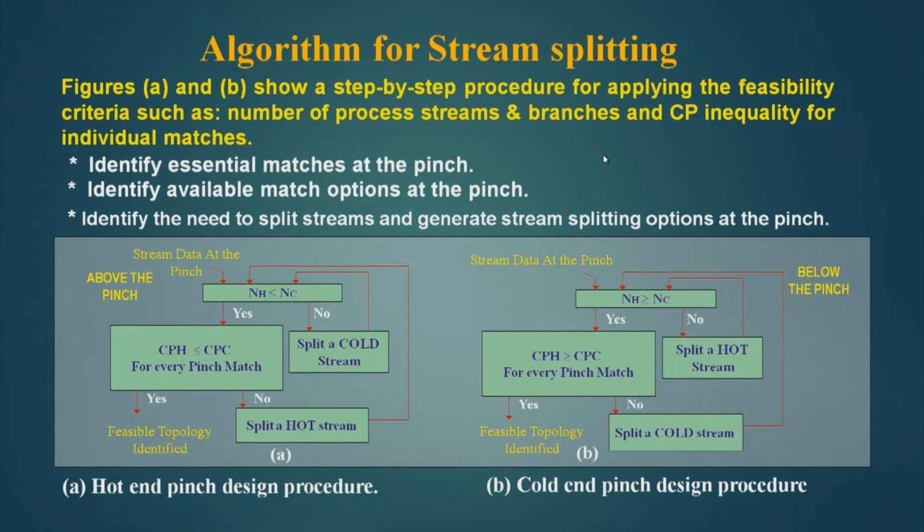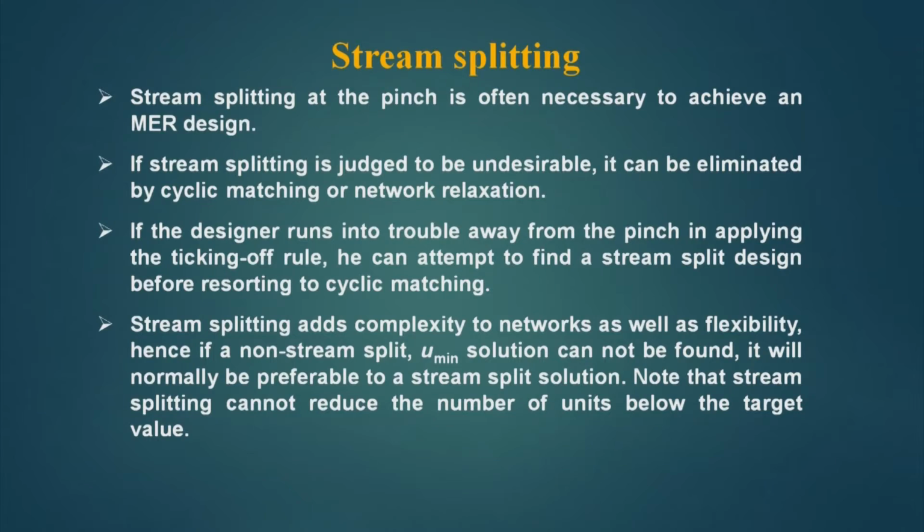So, our basic approach is to identify essential matches at the pinch, identify available match options at the pinch, identify the need to split streams and generate stream splitting options at the pinch. Now, let us see some problems with the stream splitting, or its advantages and disadvantages. Stream splitting at the pinch is often necessary to achieve an MER design. MER means maximum energy recovery design.